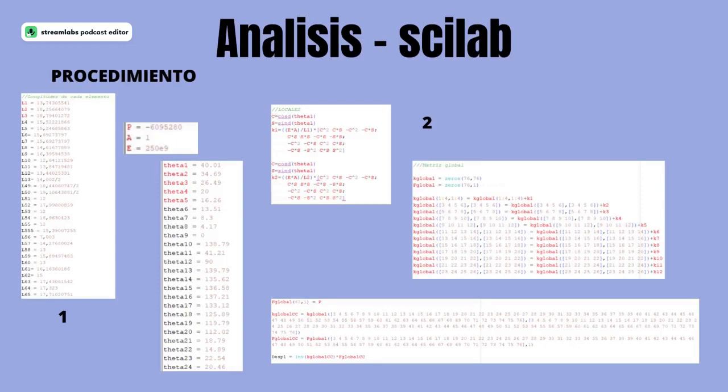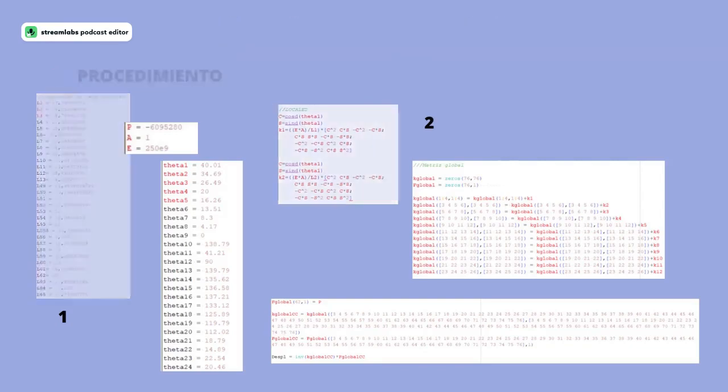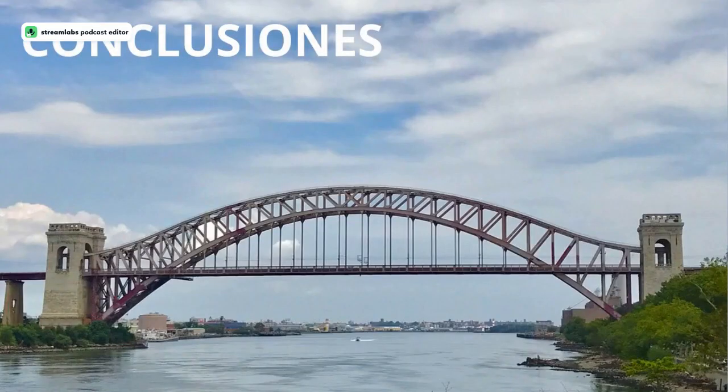This gives us 73 different elements and 29 angles. Most of them are not repeated, and with the load, the modulus and the area of a square meter, each element has its local k. We have 73 local k, and then add all these local k and their positions to the global k with each nodal position, and then extract the global k with the boundary conditions and apply them to find the displacements in the conclusions section for the analysis directly.